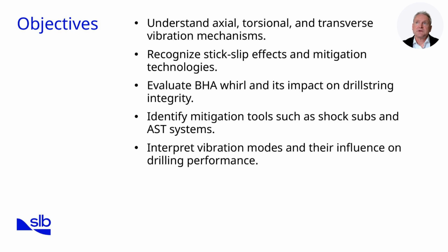In this submodule, we'll start by examining the three principal vibration mechanisms: axial, torsional and transverse. Understanding these is essential for identifying the root causes of drilling dysfunctions. We will then explore stick-slip effects, a common torsional vibration challenge, and review both downhole and surface technologies used to mitigate them. Next, we will evaluate BHA whirl, a particularly damaging form of vibration that can compromise drill string integrity and accelerate wear. From there, we'll discuss practical mitigation tools such as shock subs and advanced shock absorption systems, highlighting where and when they are most effective.